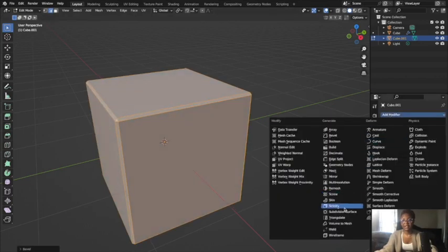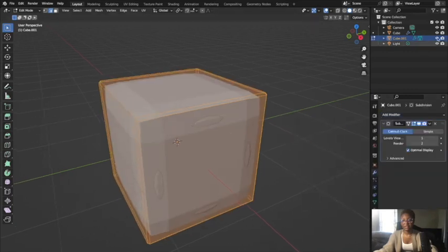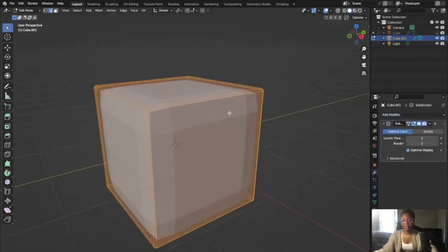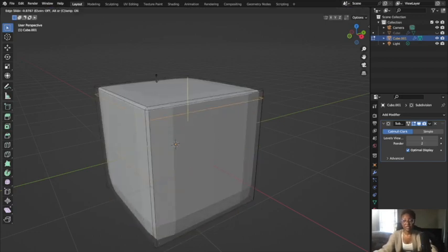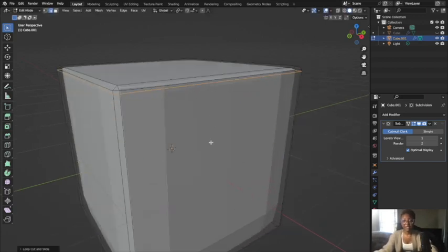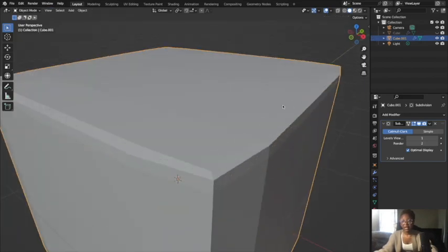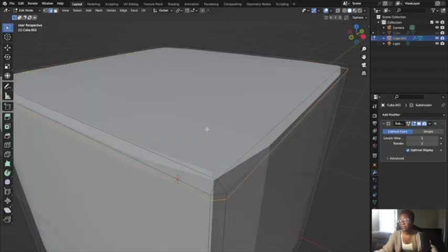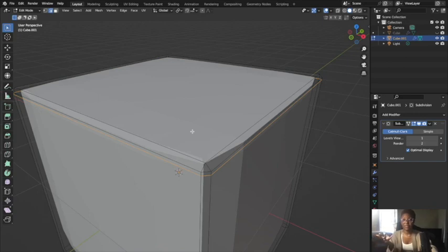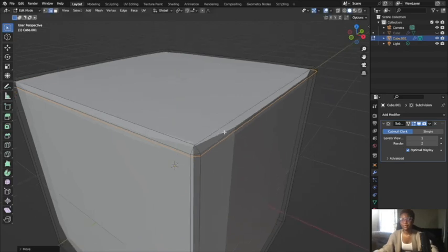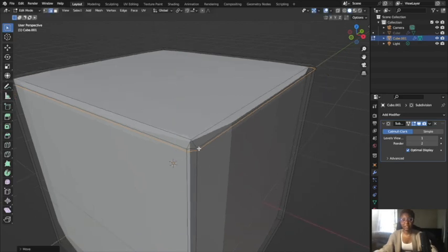and it's subdivided, it works very well with this as well. So we're just going to create a loop cut, and we can drag that up, and as you can see, it's going to allow you to manually place a loop right here. And this is ultimately what the bevel tool does. It just allows you to create extra loops to give you more support around the edges.